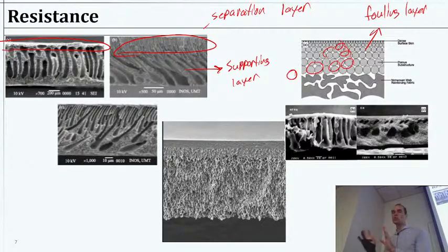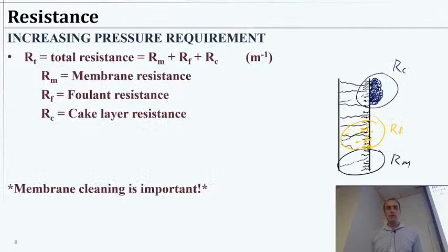But we don't usually worry about that quite as much when we do our calculations as we did with the granular filters. That's a bigger process, a lot more water to use. It's a lot more complicated than just simply reversing direction for a moment and shaking stuff off. In membrane filtration, we're also going to have that retentate stream in the first place, where we are already always wasting some water, and that backwashing is just going to get caught up in that. So we don't really have to worry about the math in the same way. Okay, so that's kind of what they look like.